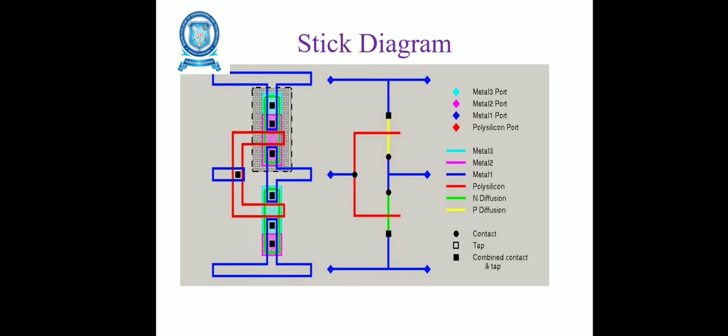Here the polysilicon layer crosses the diffusion layer, and you can see that the transistors are created. Design rules are the communication link between the designer specifying the requirements and the fabricator who materializes them. The first set of design rules was introduced as lambda based, and mask design is aimed at turning a specification into a mask for producing silicon to meet the specification.